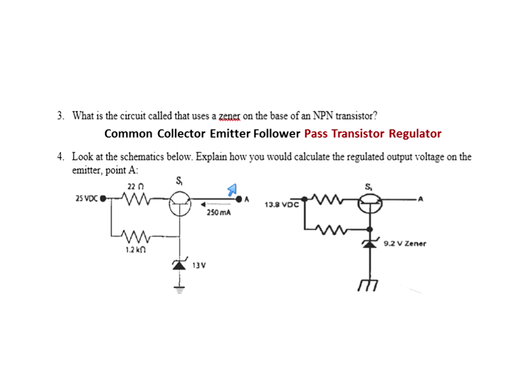Okay, look at this one, the one on the right. It's another tricky one. I've got 13, 14 volts coming in. What am I going to get out here? How would I solve this? First, find the voltage on the base. It's given, 9.2. Subtract 0.7. What is 9.2 minus 0.7? You would estimate the voltage on that terminal to be about 8.5 right here.